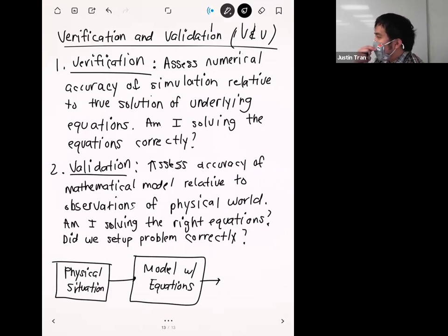That step is one we've kind of looked over a lot in this class. But if you think about when you open up ANSYS, you have to select an analysis system to work with, right? Most of the time we pick static structural. When we pick static structural, we're assuming that the situation is static and it follows the equations of linear elasticity. But there are other options too, like the dynamics we've seen, and what you'll see later, modal analysis. You have to choose or develop an equation that models your system.